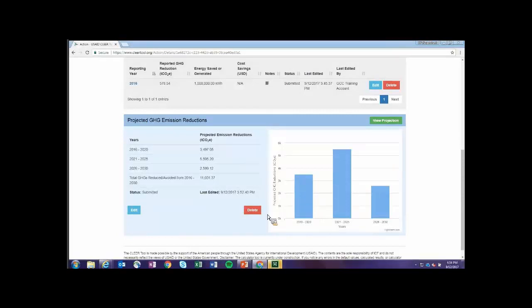So yeah, thank you for this question. This is a good one. We use country-specific grid emission factors, and these are also marginal emission factors, so they take into account both the build margin and operating margin, essentially what is the electricity that is most likely to be displaced as opposed to the grid average. I think the protocol talks more about some of the definitions behind these, so you can look there. But yeah, we use marginal grid emission factors updated through the latest CDM projects.